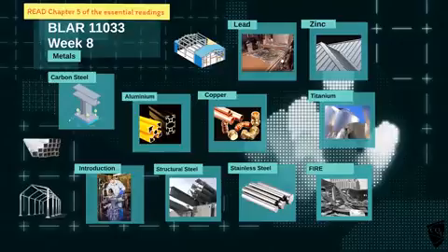But you probably said that is the traditional way of making sheet lead. So they heat the lead up in a cauldron here. This is a bed of sand. They pour it out, and it's at an angle, and that starts running down, and then they follow it down to flatten it. Two blokes go walking down, flattening it, and it's collected in a trough at the other end to be recycled round. This is a typical zinc roof, not colour bond roof, that's a zinc roof.